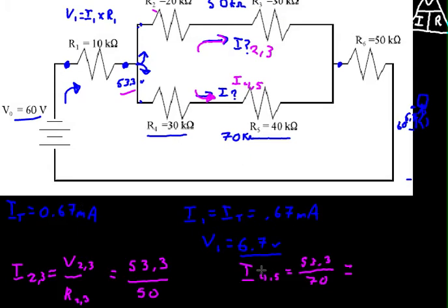And you can also use those I's, and multiply them by each individual R to get the corresponding voltage drop between each one of these points. So there'll be some voltage drop here, some voltage drop here, some voltage drop here, some voltage drop here, and in the end, whatever these points are, this is all as if it's just one point.